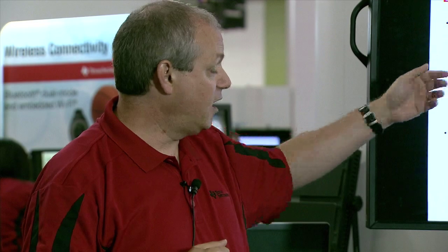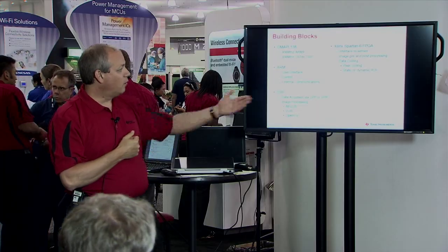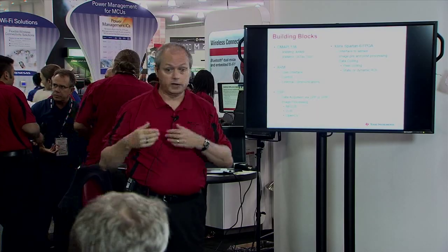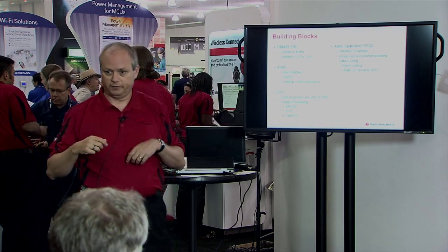A couple of different ways that we cull that data down is we do pixel culling. So you can have the FPGA searching through the image data as it flies through the FPGA and cutting down the pixels that get passed on to the OMAPL138. When it finds a feature that it thinks the DSP or the OMAPL138 is going to be interested in, it clips that piece out and sends it on. Or you could implement a static or a dynamic region of interest using the FPGA itself.